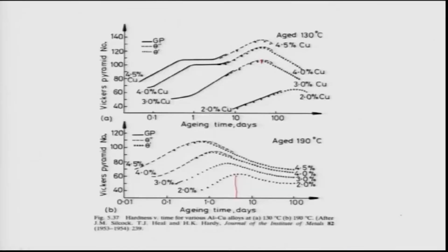So, that is the main reason why you see such aging curves in the microstructure or in the real heat treatment. Therefore, if I want to create a good material which will be applicable for various potential applications, we need to have a combination of good hardness and ductility, and that is only possible when you are on the rising side of the curve. That is what I am showing you here in all the cases.